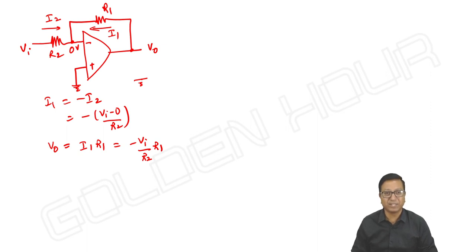However you do, we get it. Earlier nodal analysis, here also nodal analysis only. So in case of an inverting amplifier, the voltage across the feedback path looking from output to input can be taken as your output. This is one interesting point of observation. So I am writing that statement.